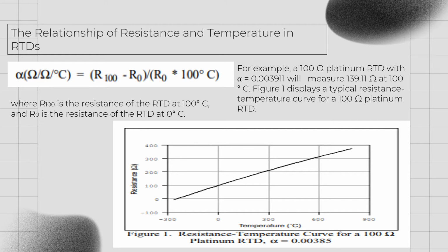Compared to the other temperature device, the output of the RTD is relatively linear with respect to the measured temperature. The temperature coefficient called alpha differs between RTD curves, although various manufacturers may specify alpha differently. Alpha is most commonly defined as the change in RTD resistance from 0 to 100 degrees Celsius divided by resistance at 0 Celsius divided by 100 degrees Celsius,